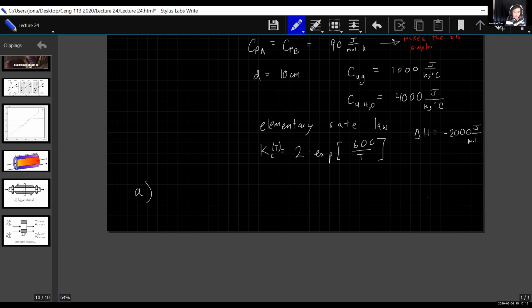So part A is going to be, if air is used as the cooling utility. I specify cooling, by the way, because del H is given as a negative value, which means that the reaction is exothermic. And if the reaction is exothermic, then obviously our heat exchanger is not going to be heating the system, because then we'd potentially just get a runaway reactor and cause an explosion.